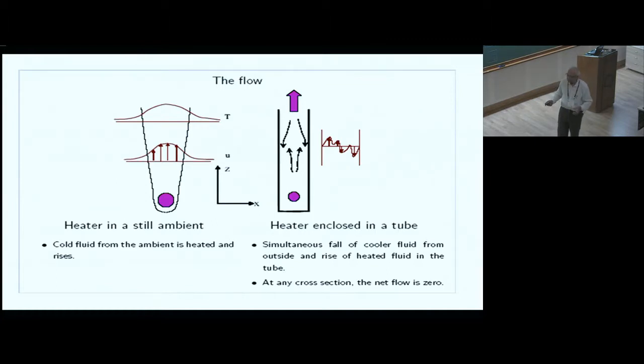So it turned out when we did the experiment, it was quite unexpected. So like you said, it will go off after some time. But if the tube length is correct, then it would burn for a while, then it would start flickering, but not go off. Then again, there was a periodic behavior, it would never go off completely if the height was right. But of course, if the tube length is higher, then it would extinguish. And if the tube length is shorter, then it won't extinguish because there is enough ambient air coming and feeding the candle.